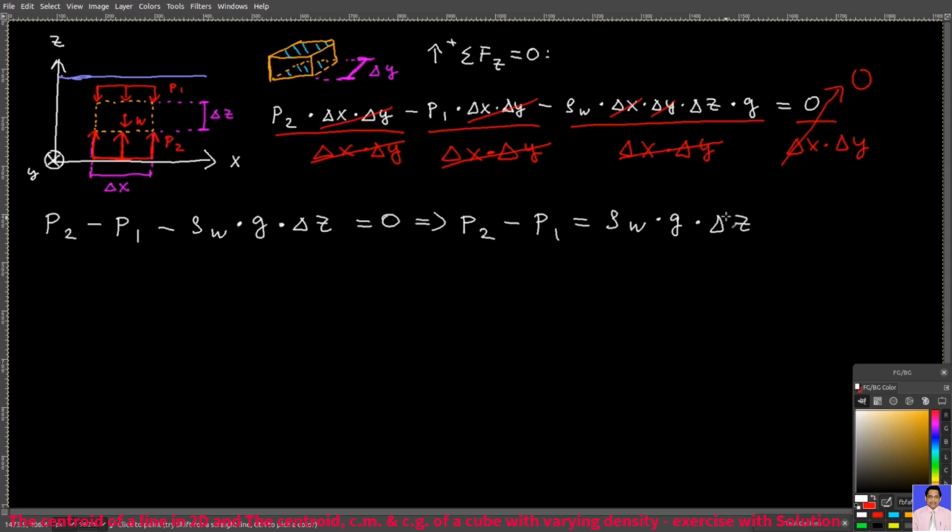You can see that it's a linear function. So in this drawing, you can see that this is a linear function that varies with depth. And now, if we only consider the pressure due to water, meaning that we don't include the local atmospheric pressure above the water, then at 0 depth, your P1 would be 0. So this is pressure due to water only.